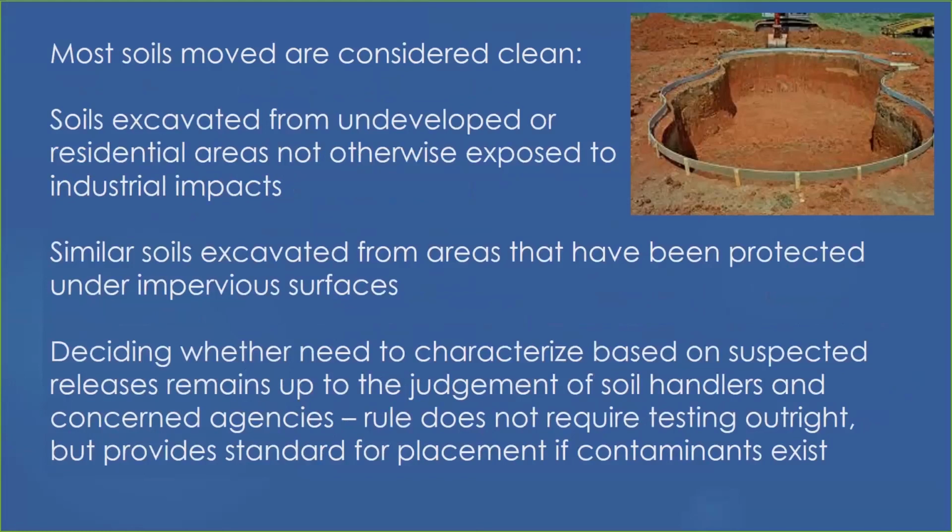Similarly, soils that are excavated from areas protected under impervious surfaces, and this has actually already come up. So if you have something that's been protected under pavement and there's no reason to believe there's been a release under that pavement previous to placing that, you can consider that soil clean. And in line with this too, deciding whether you have to characterize your material based on suspected releases is really going to be up to the judgment of soil handlers and concerned agencies if complaints come in.